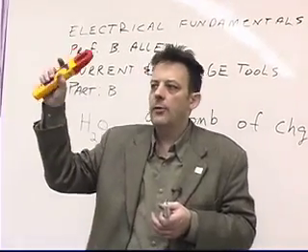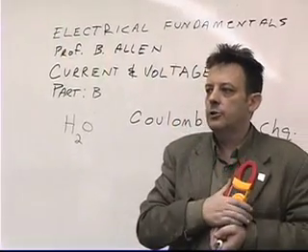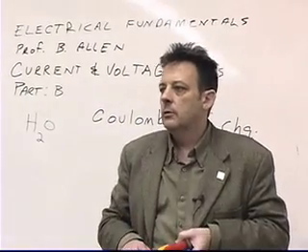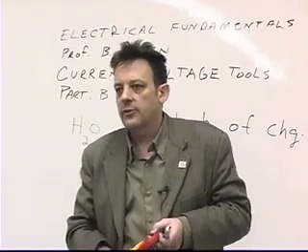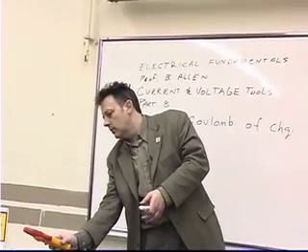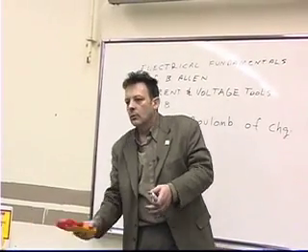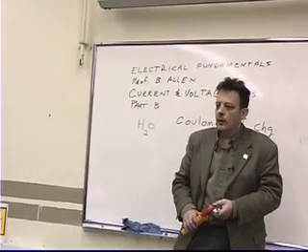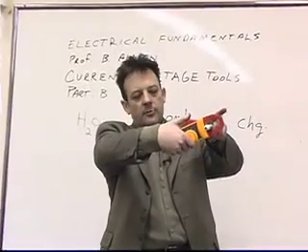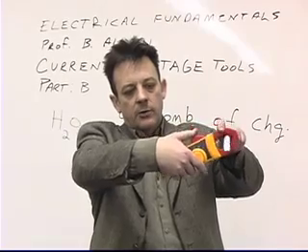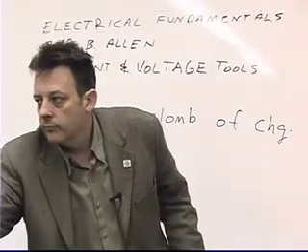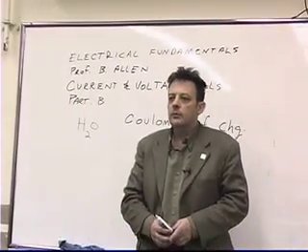And these are used all the time. I mean, if you're an electrician for PG&E, trust me, you'll have one of these in your tool pouch. And when you go up to a circuit, one of the first things that you'll do is you'll find a cable, and you'll clamp it on, and you'll go, oh, okay, that's dead. Or, that's something I don't want to touch. That's got a lot of current in it. Okay? So let's say that we checked out this wire with this meter, and we saw that, aha, there's 600 amps of current flowing in the wire.